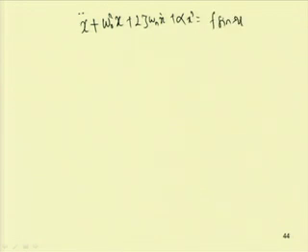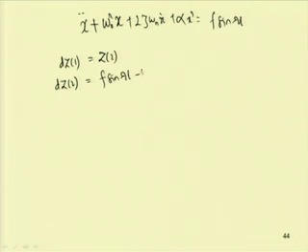In this case one can write two equations: dz1 equal to z2, and the second equation dz2 can be written in this form: f sin omega t minus omega 0 square z1 minus 2 zeta omega n z2 minus alpha z1 cube.